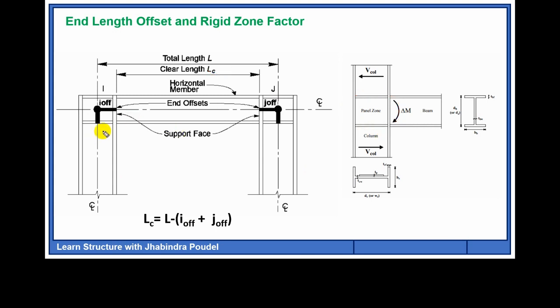If the structural element dimension is small enough, the significance of this offset length is not much, but in the case of large structural elements having large dimensions, the offset length at each connecting node should be considered in the analysis.